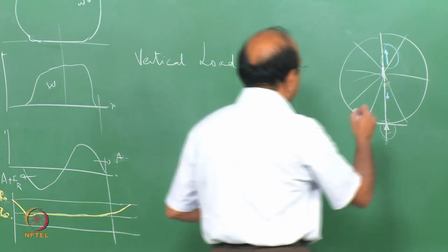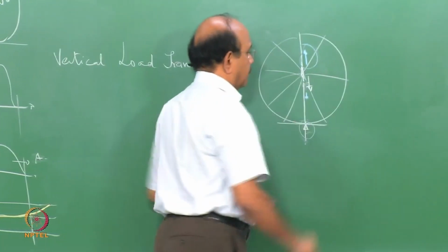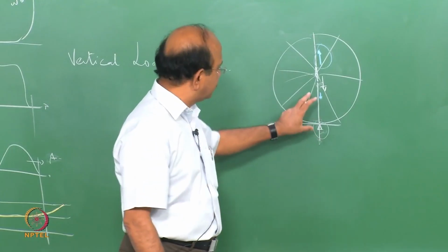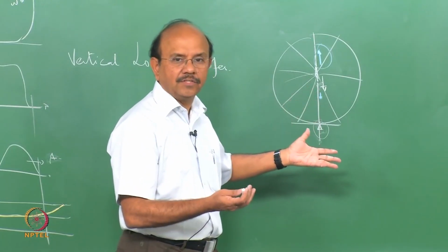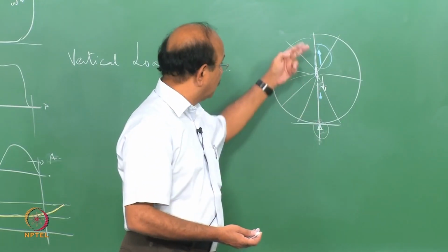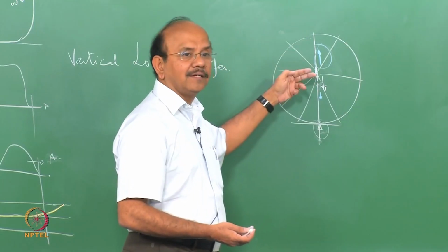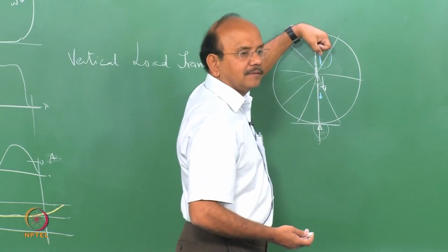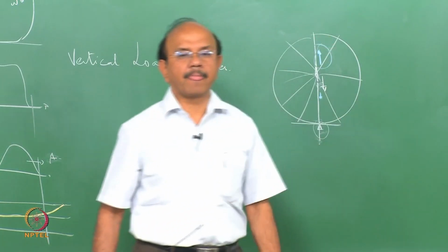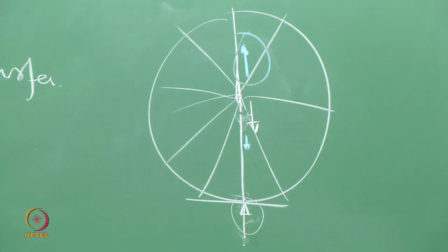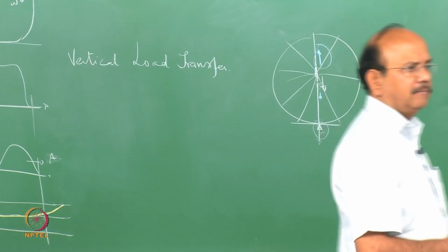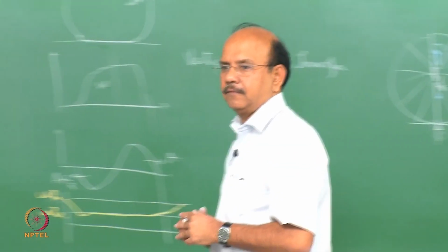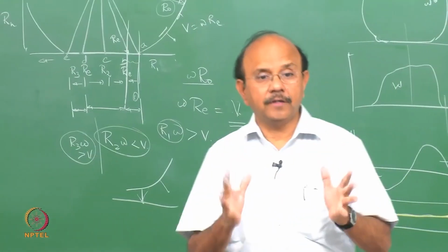So there are a number of forces. That's the load that's acting, and there is a spoke which has an initial tension. It's the ground. So the equilibrium demands that the whole wheel hangs the axle from the top. This is exactly what happens in a tire. But who plays the role of the spokes in a tire? It is the sidewall of the tire.